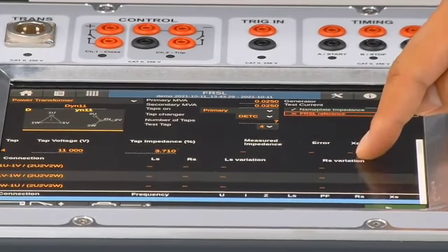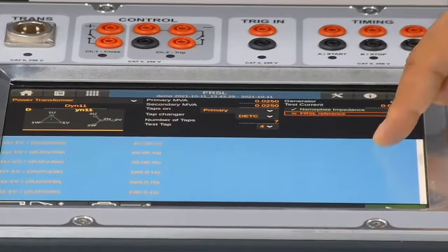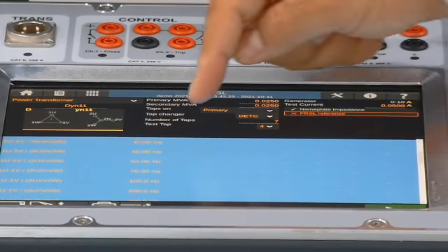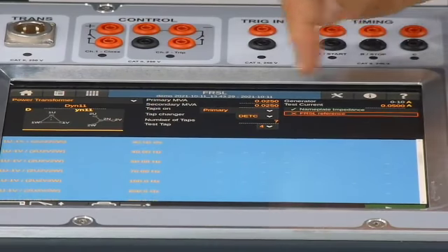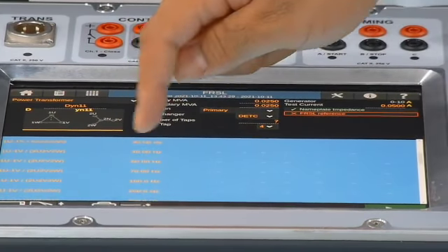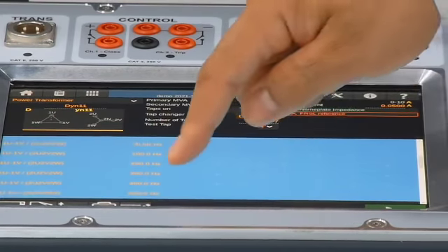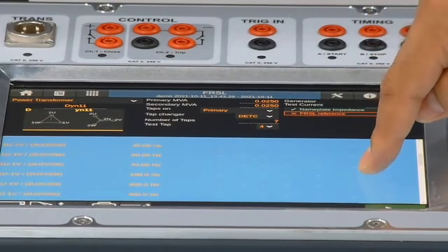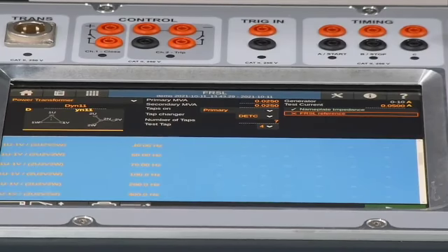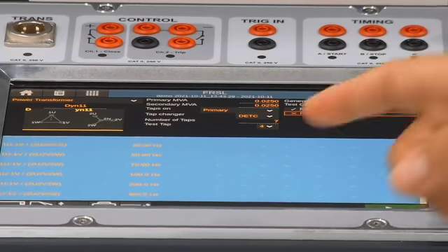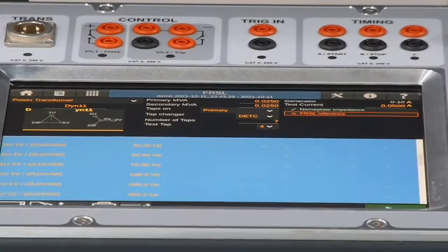I will just need to scroll down here and show you that it is highlighted here, injecting that amount of current at 20 Hz for the first phase, and here increase the frequency until 500 Hz. So frequency response of stray losses will address for me any issues related to the sound of the terms of my power transformer. That's why we go and change the frequency, looking if we have increase in eddy current within our core.